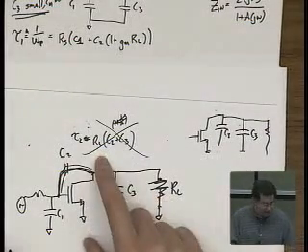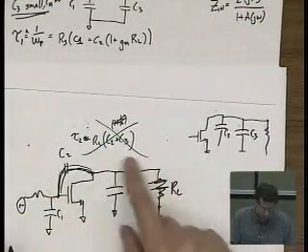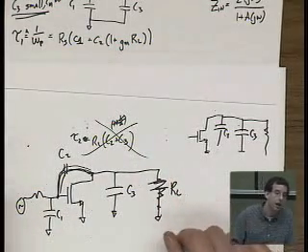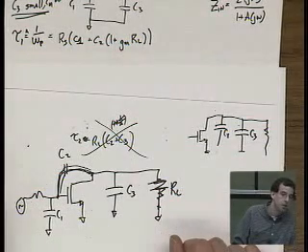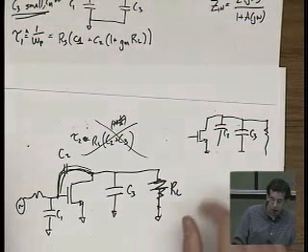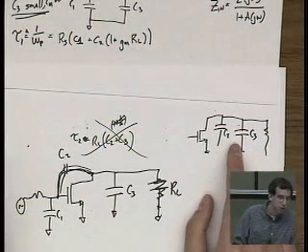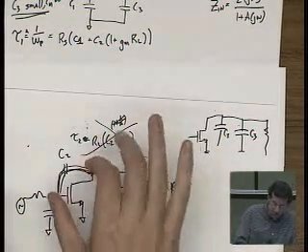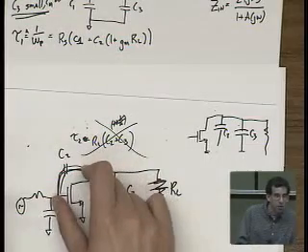And the point is that that's going to change the nature of the circuit analysis. Yeah. Assuming that C3 is really small? What's that? Is C3 still small? C3 is still small, yeah. Like RL, yes. So this is after you go in and you calculate CGB and you find that it's huge. Then you know that, oh, it's going to get shorted out. Yes, because this capacitance is getting Millerized.